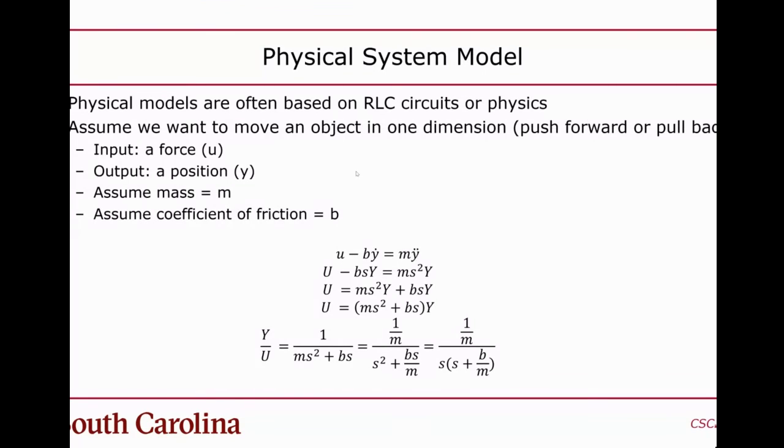I also talked about how to take a physical system and convert it into a transfer function, or an LTI. And generally speaking, this is going to be based on physics, just force equations, using force as the units, and then, for example, y is your position in this case.